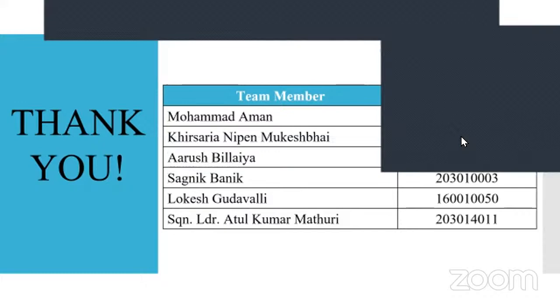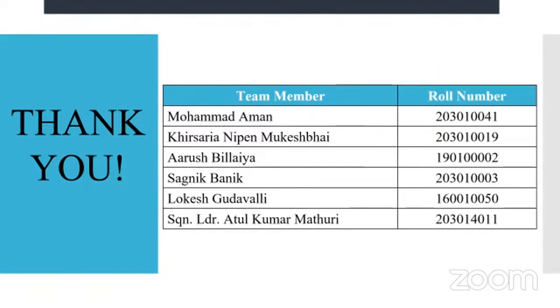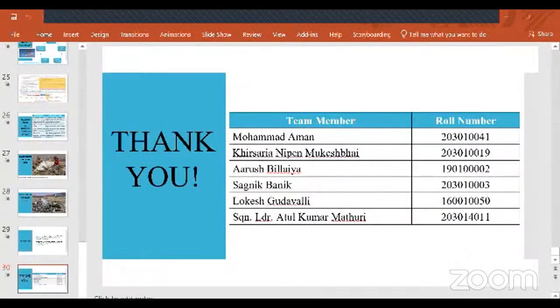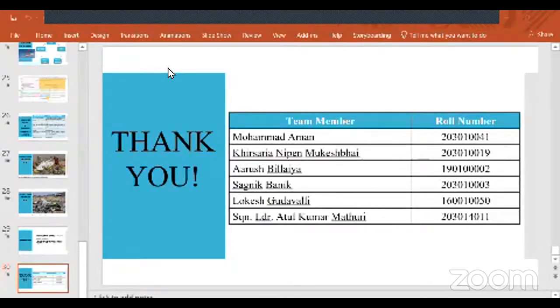Okay, so Saran here. Can I answer this? Yeah, go ahead. So when they switched off the electrical trim tab switch, they also disabled MCAS with it. But whenever we disable the electric trim system, we have to apply force manually to turn the stabilizer trim. With the stabilizer trim at a particular angle such that the aerodynamic forces were high, they weren't able to manually change the angle because there was a load of around 90 pounds on the horizontal stabilizer.